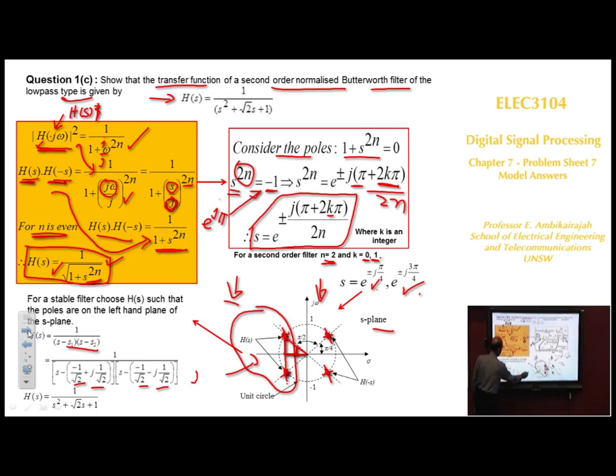If you simplify, if you multiply them out, that's what you get. That's your second order filter. This is just a simple example of how you find the transfer function of a Butterworth second order filter. So you start with the Butterworth magnitude function and work your way through.